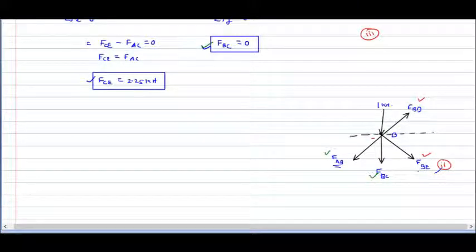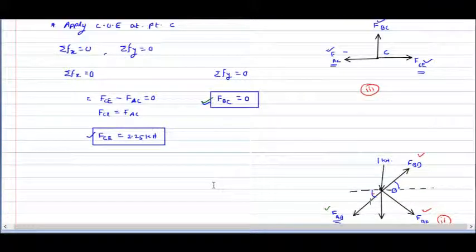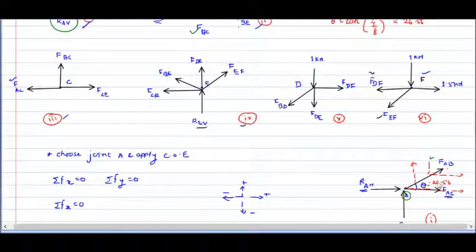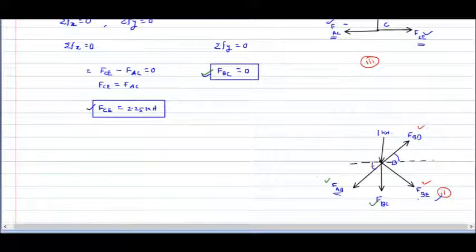While solving this problem, once again we need to trace out the angles of force in member BD and force in member AB. Already we have calculated the angle of force AB as 26.56 degrees. And force in member BD, its angle will also be 26.56 only, because from the geometry we can see AB and BD are along the same line.